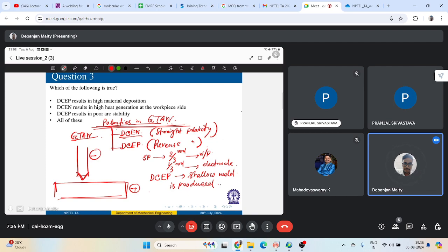Now, in terms of electrodes, those tungsten electrodes are coated basically. They are coated with some cerium or thorium to have better electron emissivity, right? To have better current carrying capacity, and to get more resistance to contamination than what pure tungsten electrode can provide.